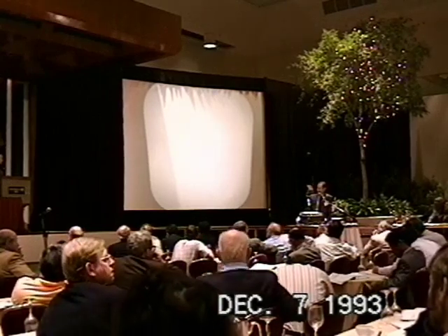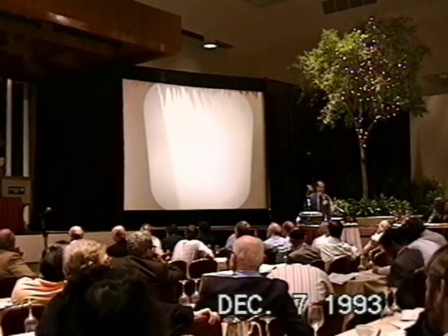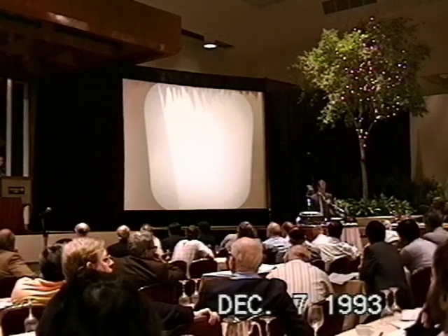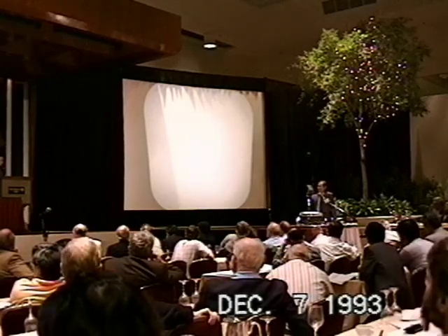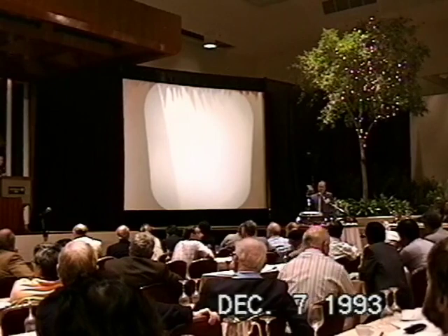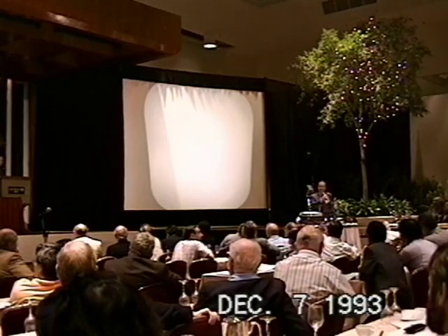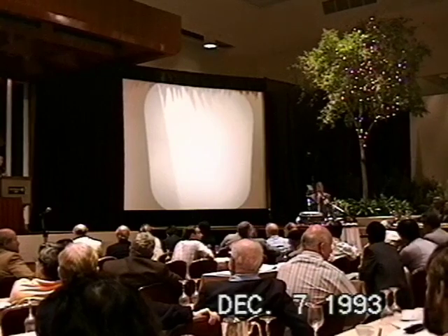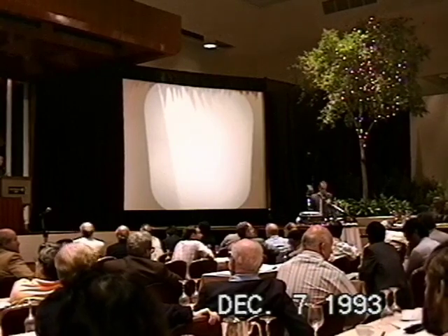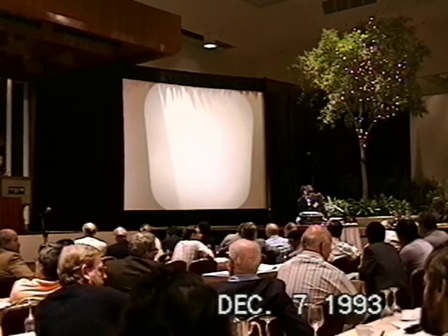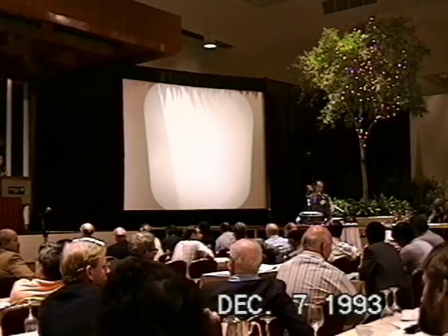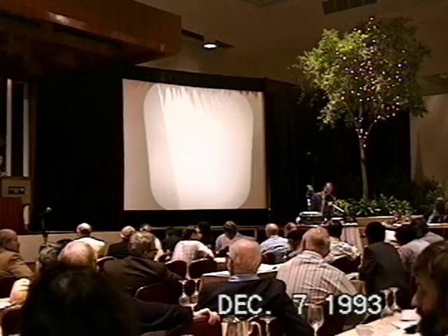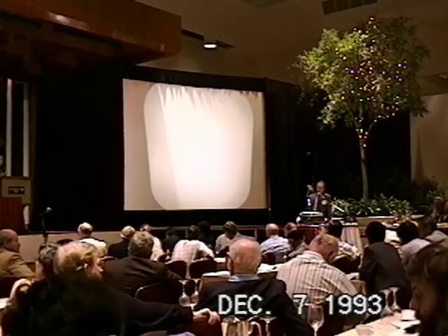No, but all the wire that we looked at is recrystallized, and I think the temperature is the hottest when we dehydrate it. So we run a DC current through it, we may get it up to 300 degrees C. At that point, that may be good enough to recrystallize it. So I'm not sure there's any magic to having it being pulsed, but at the end of the run, to get all the hydrogen out, we do dehydrate it.